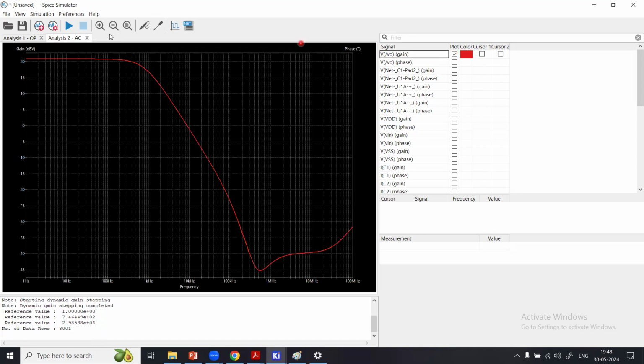So now you see I have got a gain of about 21 dBV. If you compare this plot with the plot we obtained in our previous module, the gain was 0 dBV, because in that module we used the op amp as a voltage follower or voltage buffer. We don't have a gain there, but this time on your screen we have the op amp configured as a non-inverting amplifier. We are using an amplifier, and we are also therefore creating a filter circuit.